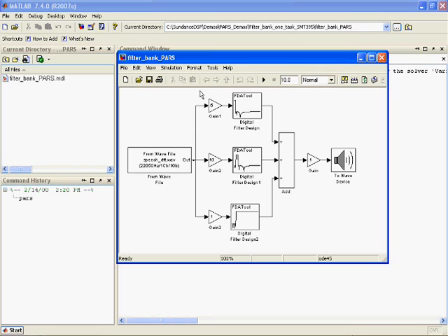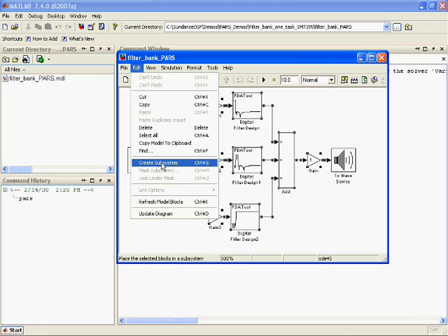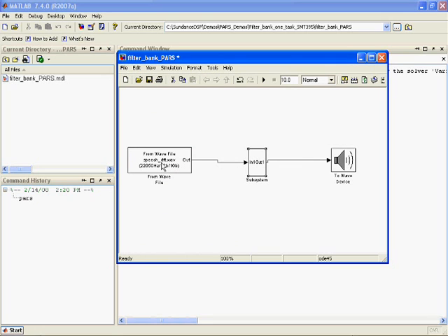As we were only interested to have one task on the DSP, we are going to select all of the blocks except the ones which are going to be running on the host. At this stage, we ask PARS to create a subsystem for the blocks we have selected. As a shortcut, you could press Ctrl-G to create the subsystem. The window now shows the subsystem and the 2 blocks destined to run on the host.